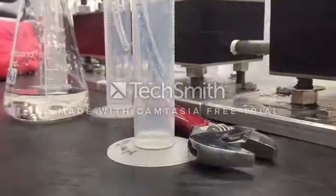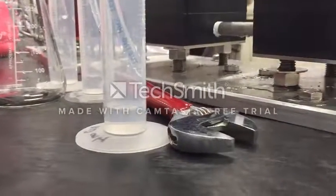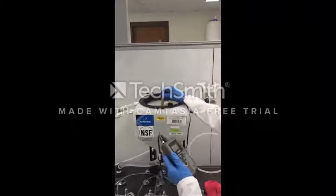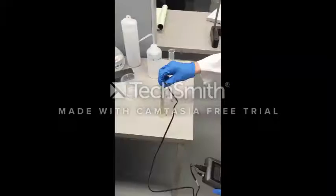Collect samples from each of the cells simultaneously. Ensure collection times are sufficient for accurate conductivity probe measurements. Also, note the conductivity of the feed tank. Repeat this process for additional system pressures and RO membranes.